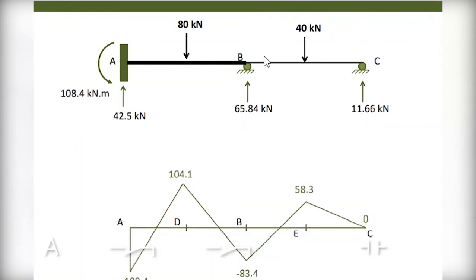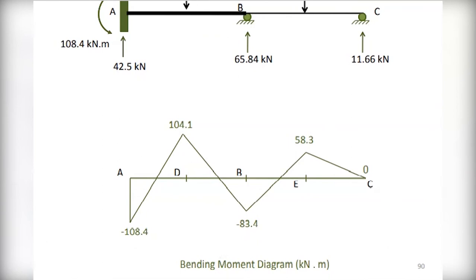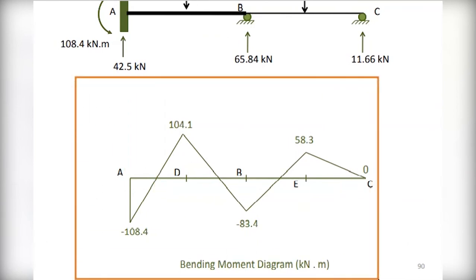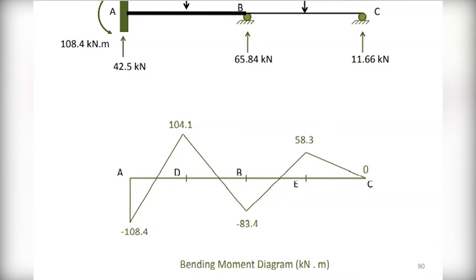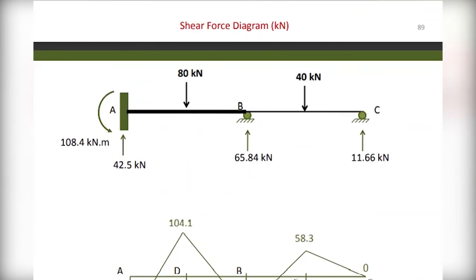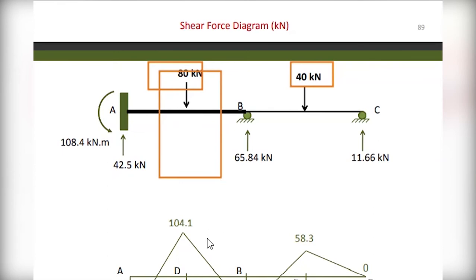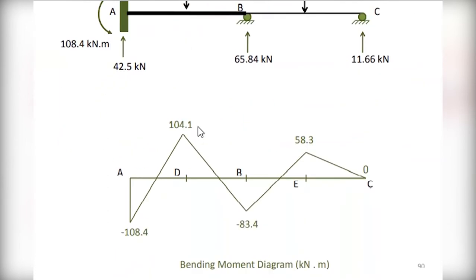So your bending moment can now be created there, as you see here, and this is the value of the bending moment. You can see the maximum bending moment is at the middle of the load, because the magnitude of the load here is bigger than this one. Automatically, at this point the maximum bending moment should be created at the middle. So go on and create your